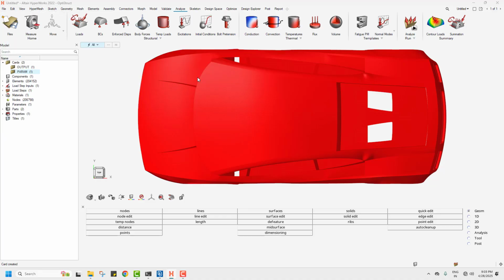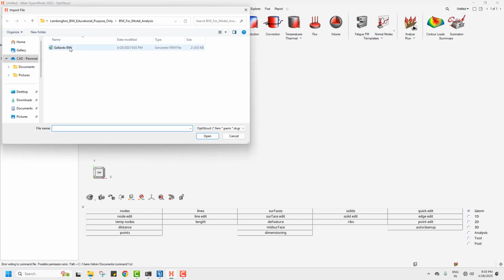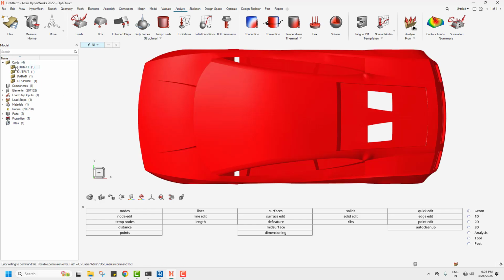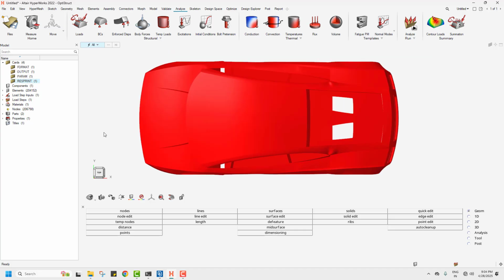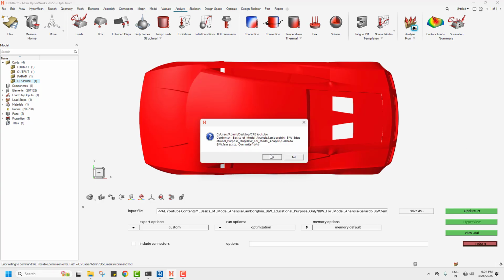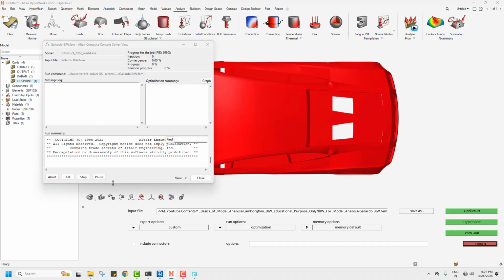Okay, just discard this. You can just open solver deck. Okay, this is the one. You could see the timing, this is matching. Just load it up here. Once you load it, you could see we have all the cards here, output, param card, okay, and then the result print, print all results. Fine, so now I just need to run this. Let us see now. Just click on this, output, override it, and then let's see. Now if everything is fine, it should run.